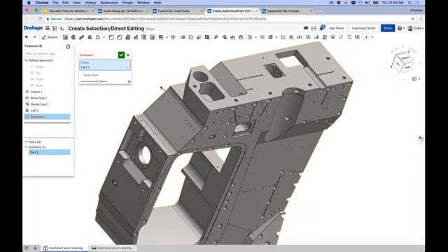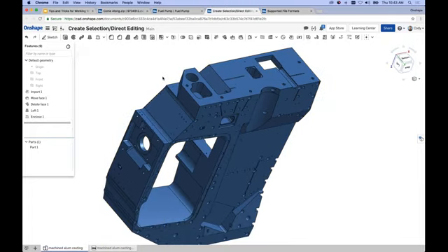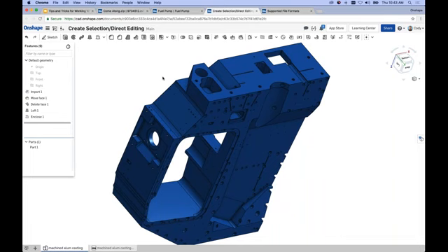So that's generally the workflow that you would take if you're going from an imported model that maybe has issues or just has a problem face or faces. You delete those faces and recreate those. The two most common commands that I know of in this workflow are going to be loft and fill, just given the nature of the model. But remember, extrude, revolve, sweep all work just as well. And assuming that helps you in this geometry, that may be the easiest solution.